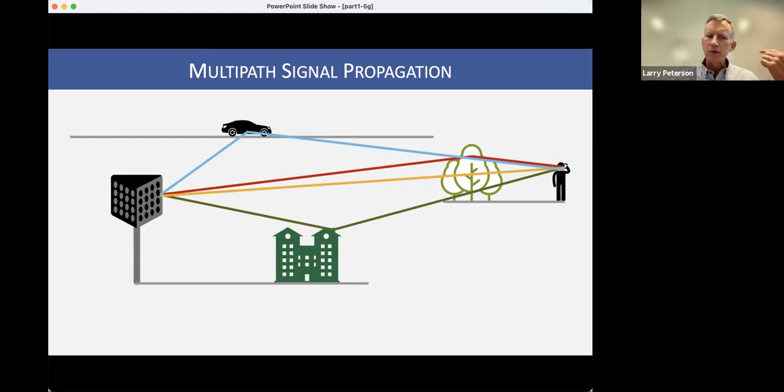But the thing that strikes me here is when I send a packet over an optical link, I'm pretty sure that it's going to make it to the other side, and I understand what the error rates are and so on. This is an extremely dynamic thing. So I have to do packet scheduling cognizant of how efficient the medium is in transmitting those packets. So it's more than just saying this packet goes in a priority queue. I have to adjust everything based upon how efficiently I, the base station, am able to use the spectrum to talk to that particular UE, and I have to do that for the entire set of UEs.